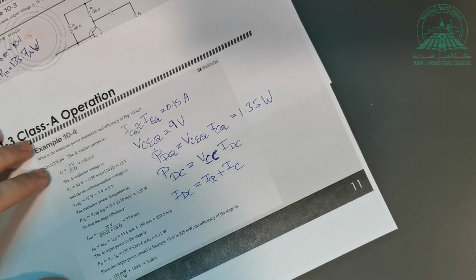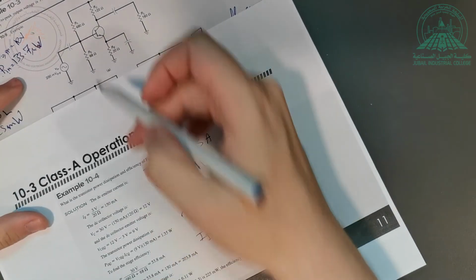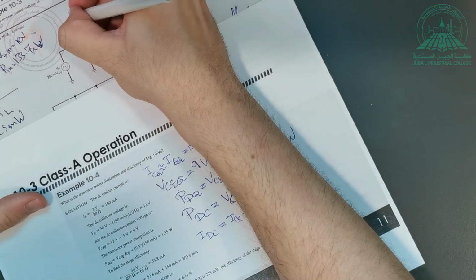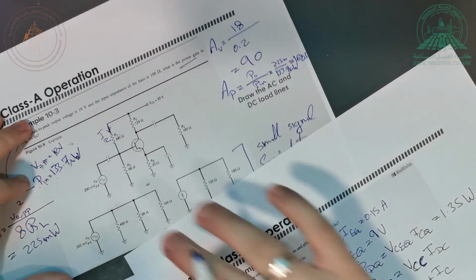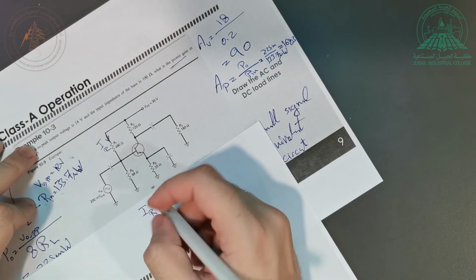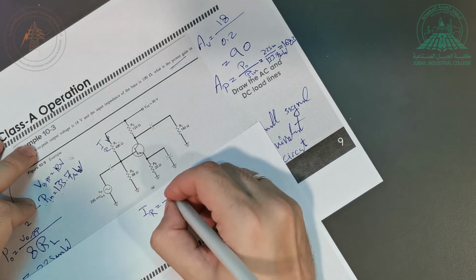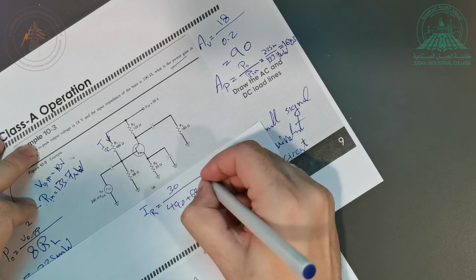Now we should make these resistors high enough, but in this case they're not that high, right? So this current IR, how do I find it? IR is equal to this voltage divided by these two resistors in series, right? So it's equal to 30 divided by 490 plus 68.